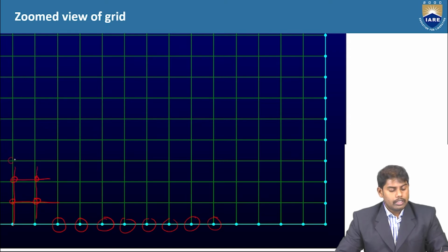So the governing equations, whatever we have, the continuity equation, momentum equation, energy equation, are solved at these grid points. What we do is linearize these partial derivatives. Let's say you have dou rho by dou t at this grid point, you will discretize and linearize it. So if you have three equations at a particular grid point, you will linearize or discretize three equations.